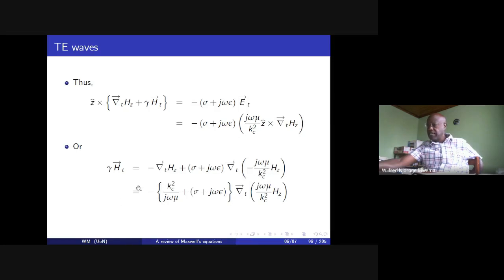And this, for obvious reasons, we are going to show that we can now interpret this, omega mu over kc squared, multiplied by that as a voltage, because this will have the values of impedance multiplied by distance. That is impedance multiplied by length, that is current divided by length, and therefore when we multiply those two together, we get a voltage here. So this is going to be an important kind of interpretation that we shall see in the following.